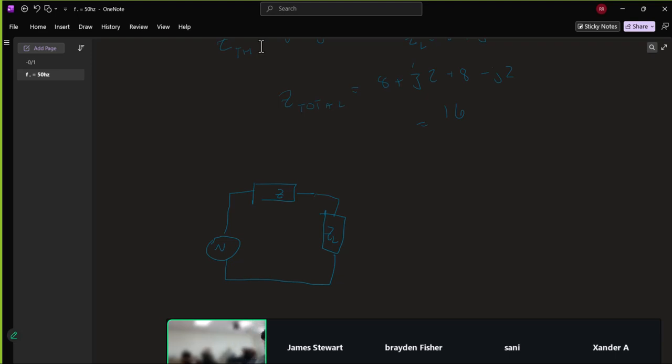Okay, so what happens is your supplied power is the hypotenuse of a triangle. That is your supplied power, and that's what you have to make. And your real power is one side. It's also called average power. And your reactive power, which you don't get any work out of, that's Q. The reactive power is the other side of the triangle, and your supplied power over here is S.